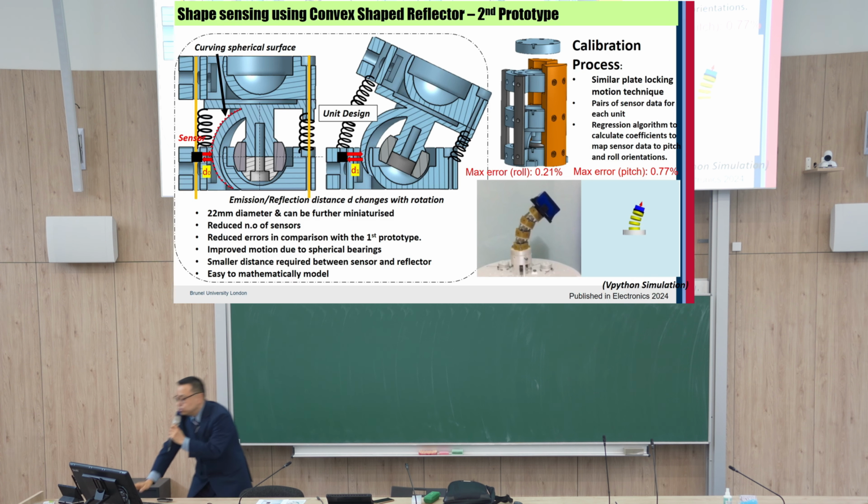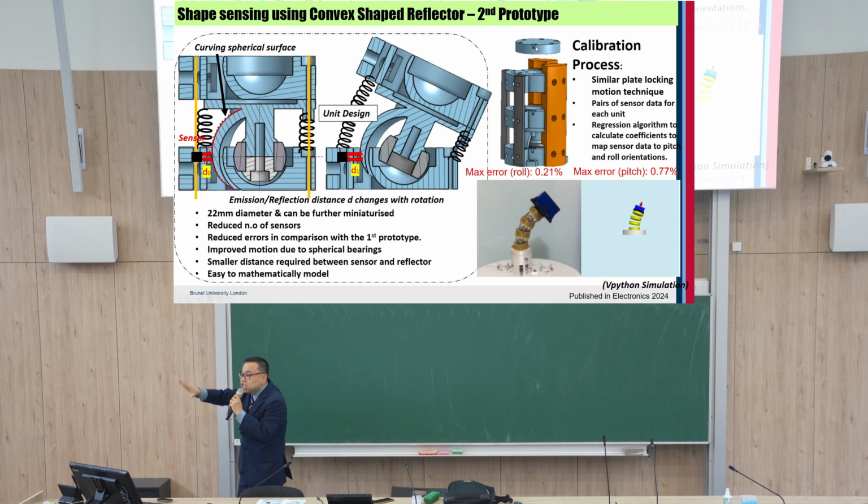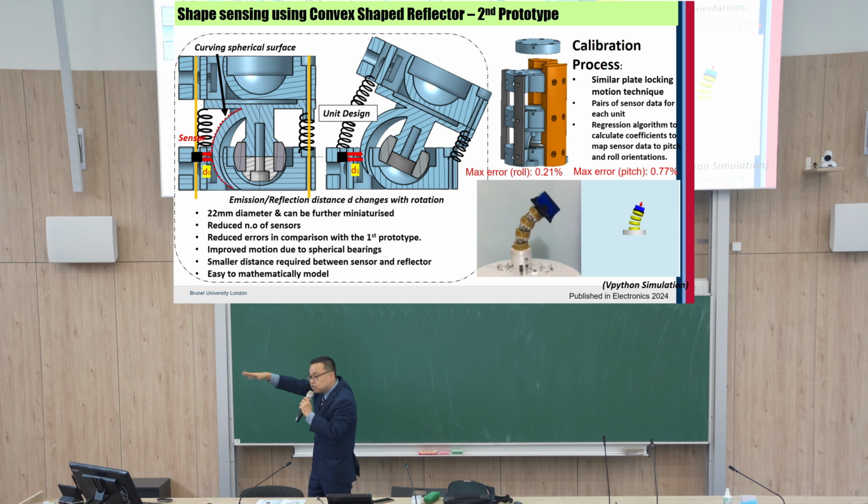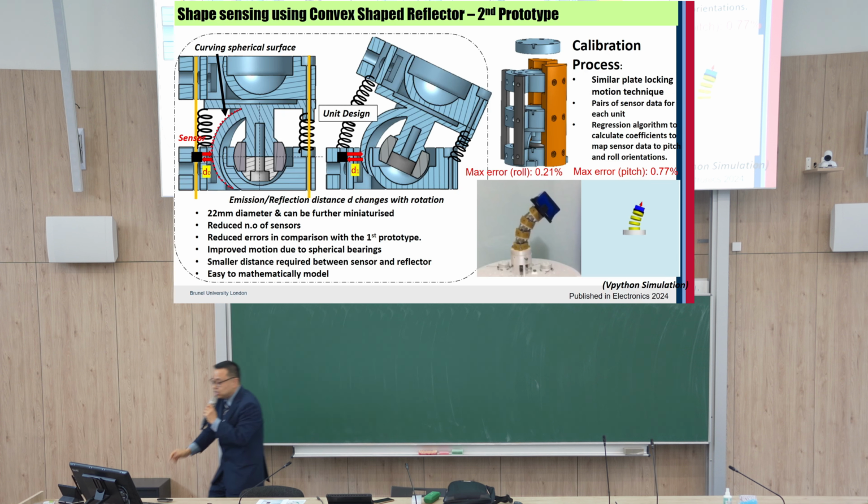And then now we put this one. This is an IMU sensor. So now unit 3 is fixed, and we regard the 3 units as a rigid structure, and solely unit 1 is moving, rotating, and then we can get IMU data, this pitch and roll data, and we can calibrate just 1 unit. After that, we fix these 2, and also fix another 2, allowing this unit to rotate.